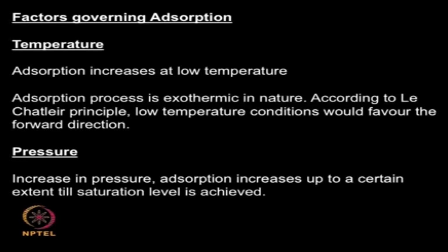So you have to be very careful in maintaining the temperature of the reaction, because it is an exothermic process, and you might have studied in your thermodynamics that for any exothermic process, it is ideal to operate at lower temperature. Pressure, we studied in detail just a few slides back, plays a very important role in the adsorption process.